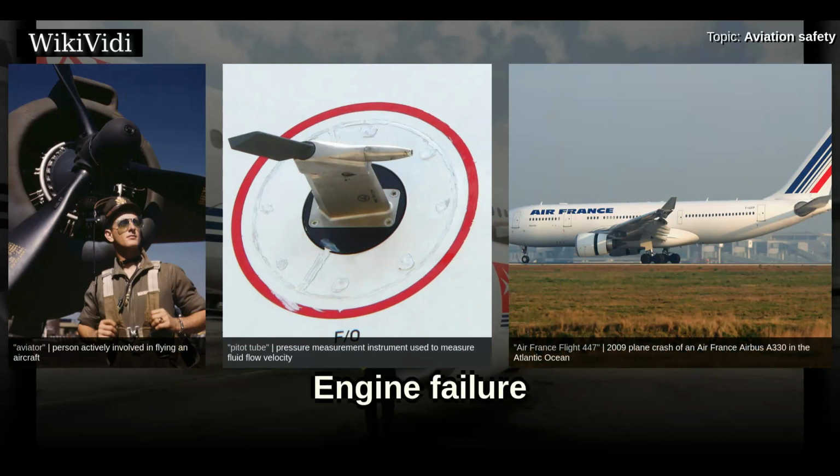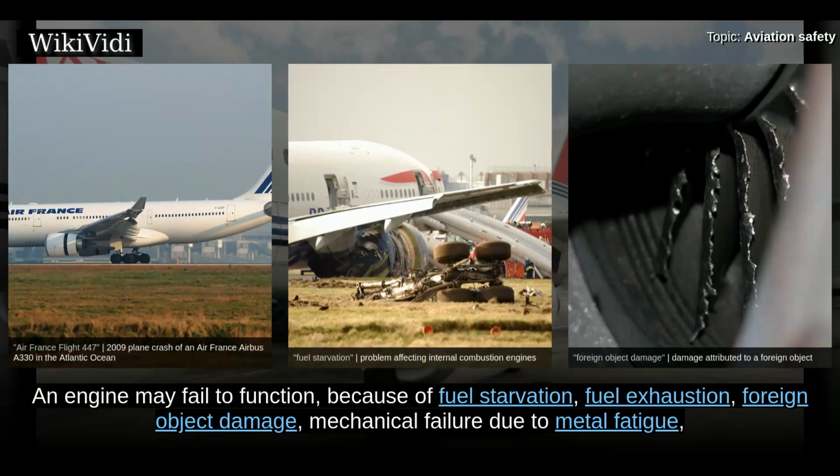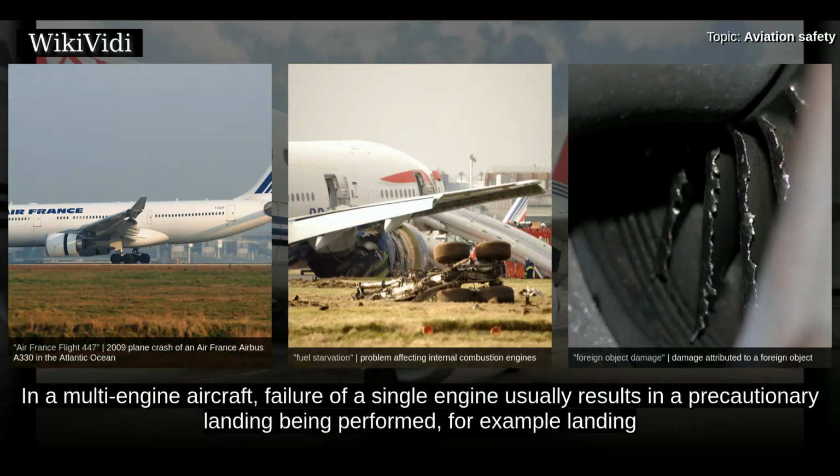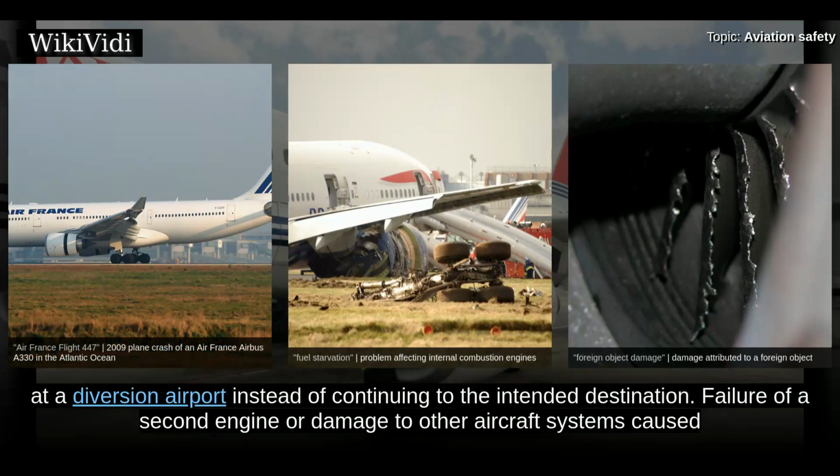Engine failure. An engine may fail to function because of fuel starvation, fuel exhaustion, foreign object damage, mechanical failure due to metal fatigue, mechanical failure due to improper maintenance, mechanical failure caused by an original manufacturing defect in the engine, and pilot error. In a multi-engine aircraft, failure of a single engine usually results in a precautionary landing being performed, for example landing at a diversion airport instead of continuing to the intended destination.